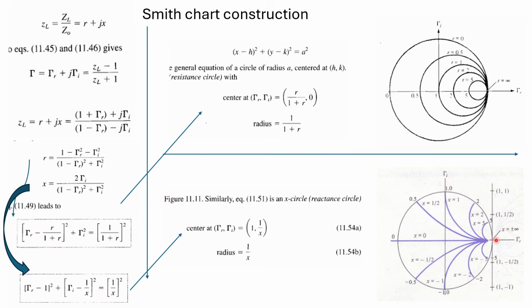As you keep increasing the values of x, the radius gets smaller. Now if you see here, your circle is divided into two parts, and this is the semi-half circle. So because of these imaginary circles only, we are getting it. Now finally, let's conclude the Smith chart construction.